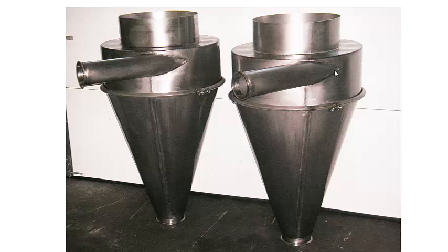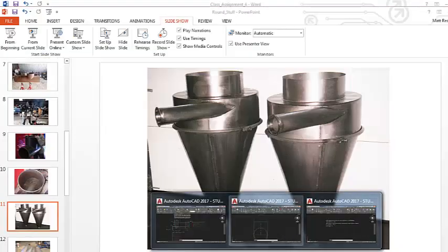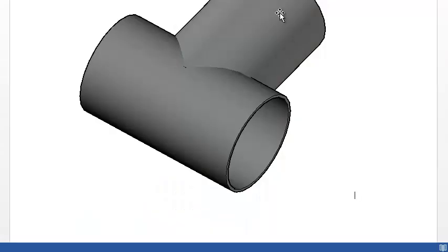So what we're going to do is start with that. I'm going to escape this, go back to my drawing page, back to my document here. We're just going to start with one that's the same diameters, and this first one we lay out will have a deep V here, where this one comes down and doesn't stop till it hits the center line of this. The branch will hit the center line of the header.